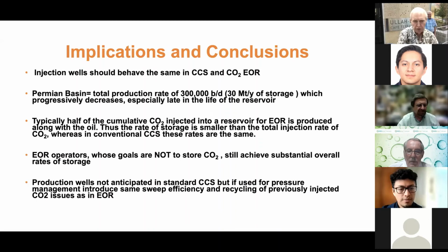Production wells are not anticipated in standard carbon capture and storage, but there's a school of thought that says we should perhaps dissolve the CO2 into water, inject the water, and then have production wells, because otherwise injecting into a reservoir that has no offtake could lead to excessive pressure. And this is going to be one of the major issues going forward with CCUS, is the difference between injecting into reservoirs that have a sealed outer boundary versus reservoirs that have a transparent outer boundary.